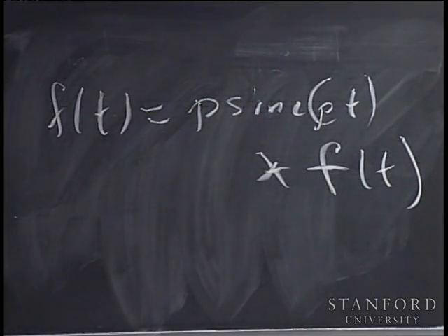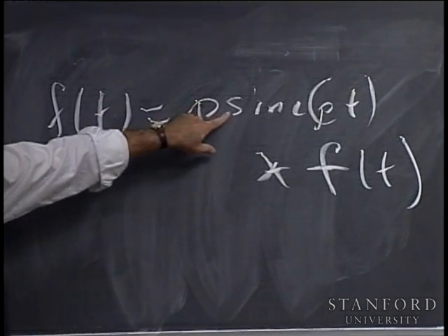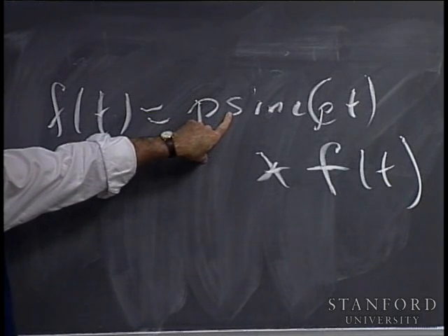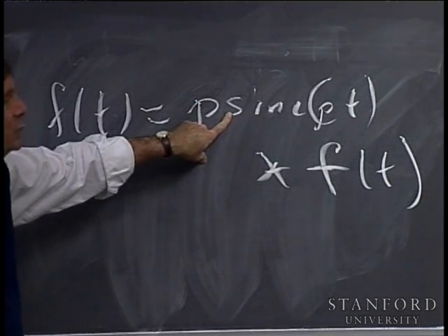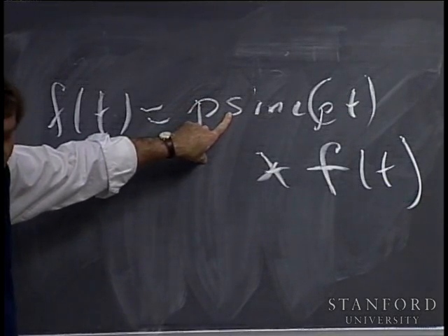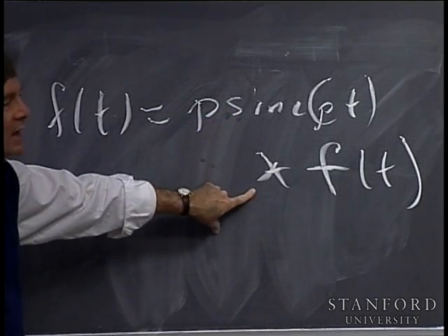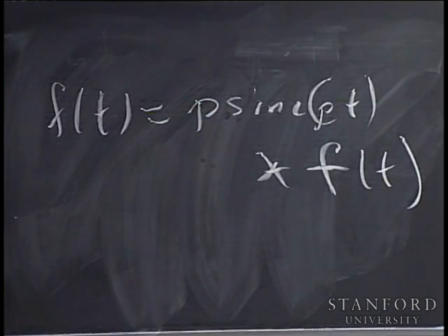It says that for these functions, the sinc function is, in some sense, functioning like the delta function, or functioning like an identity for convolution. The sinc function won't do that for all signals, but it will do that for the band-limited signals. So f is the sinc convolved with f if the Fourier transform of f is 0 beyond a certain point. Now, here's where I'm just going to wave my hands.